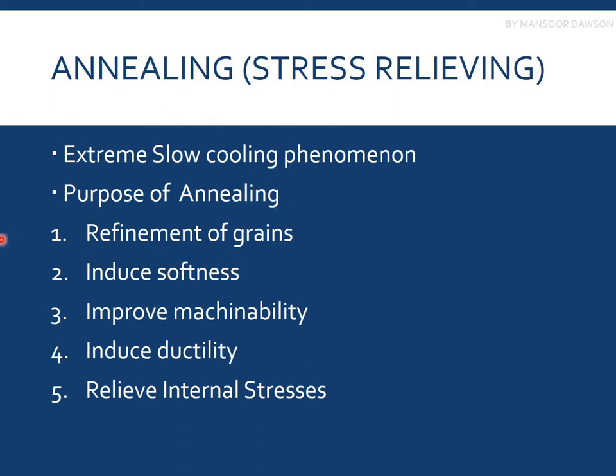Annealing also induces softness. We know that after cold working, the strength of the material is very much increased due to strain hardening. So if we want to increase the ductility now, or reduce the strength and increase some of the toughness, we'll be doing annealing.